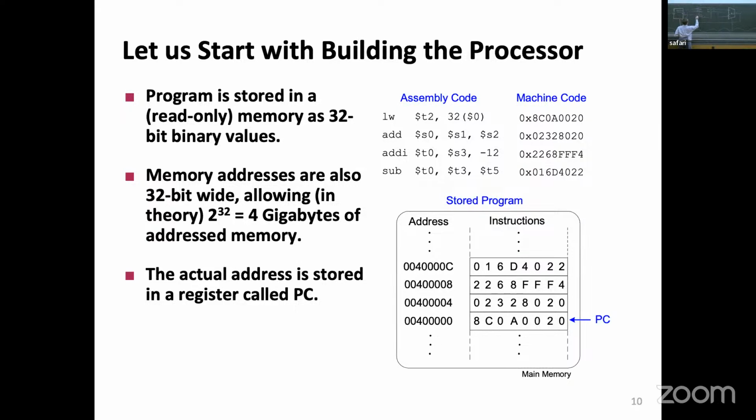And this thing is very easy because I know that the instruction bits 15 to 11 tell us where we are going to write things to. That looks ridiculously simple. I have just the instruction memory, the register file, the ALU. The program counter points to an address. From there, I get the instruction. I look at the instruction.